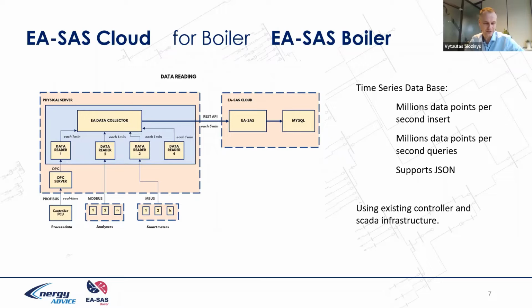It's like an OPC server next to your boiler SCADA, and we collect data every minute in real time. We collect data from your SCADA system, and if you have extra metering devices, we collect data from them too, and send all this data to the cloud every minute.